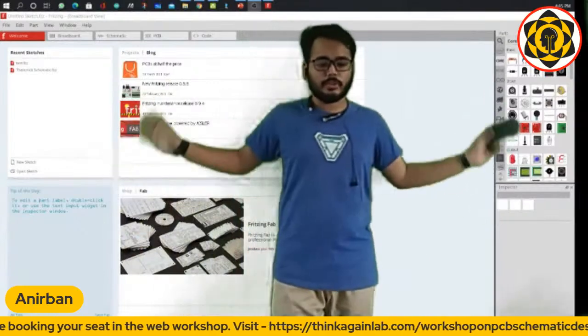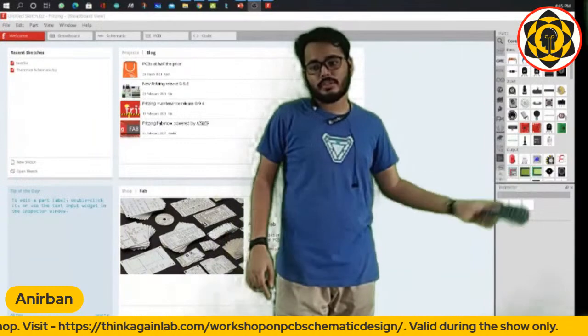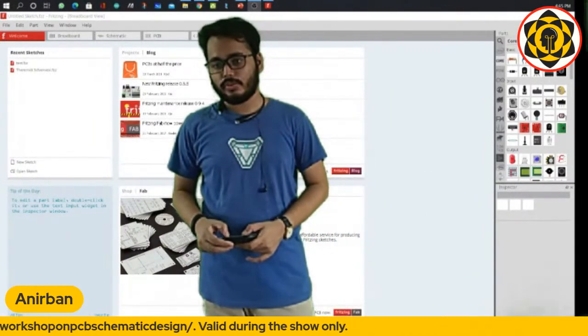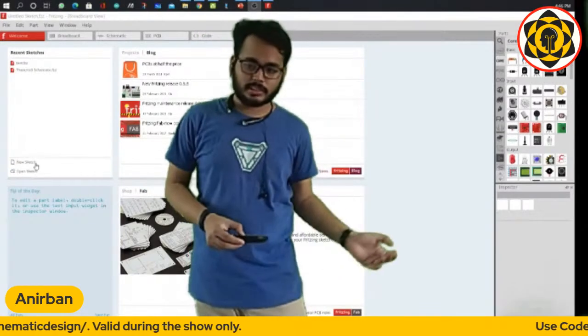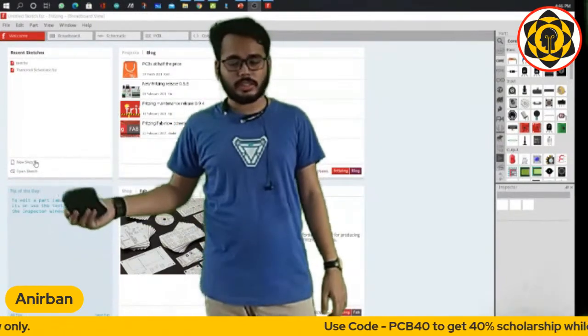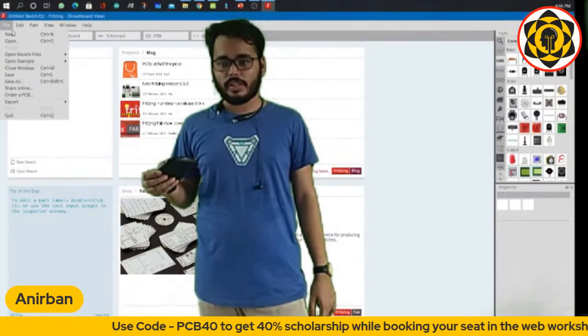Okay, so this is the UI of Fritzing. This is a welcome screen and stuff like that. To make a new circuit, just go to File and click on New. Also, you can do New Sketch, but that would mean that you first have to make a sketch. But we want to start from a breadboard perspective. So let's go to File and click on New.